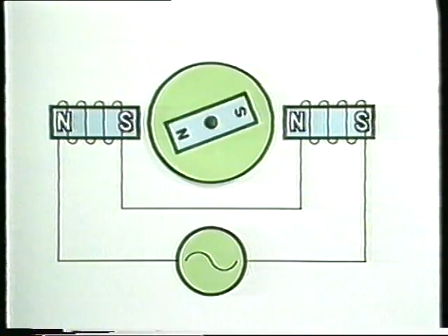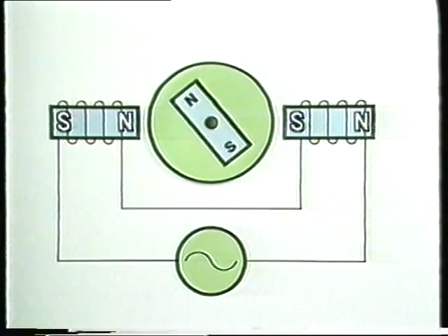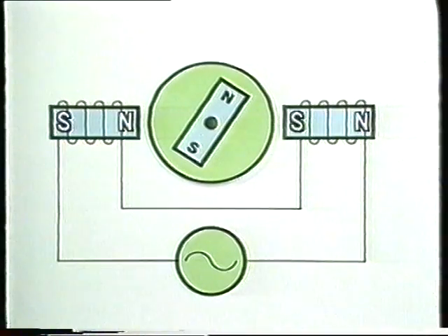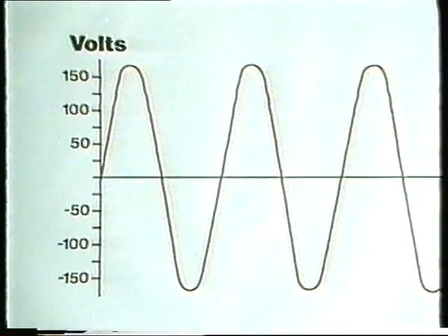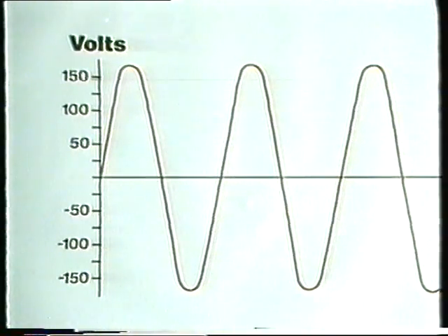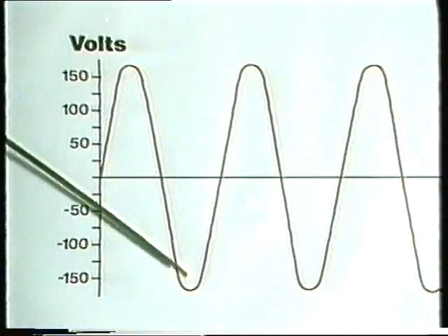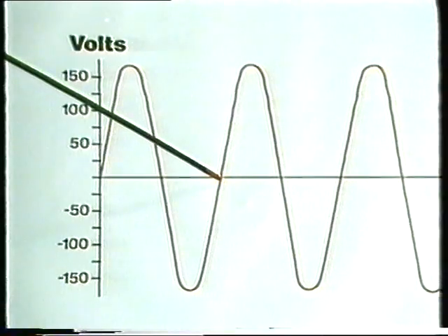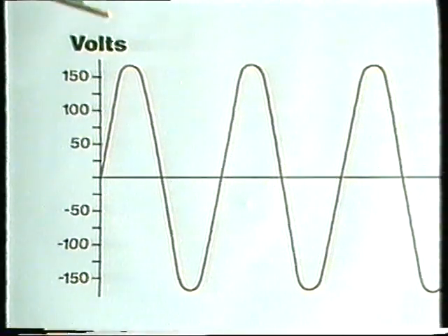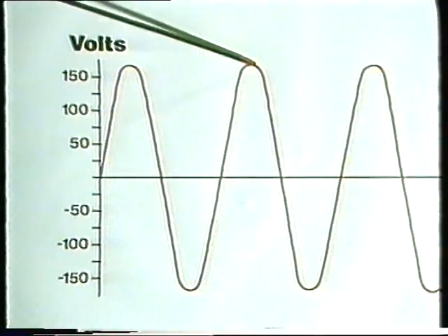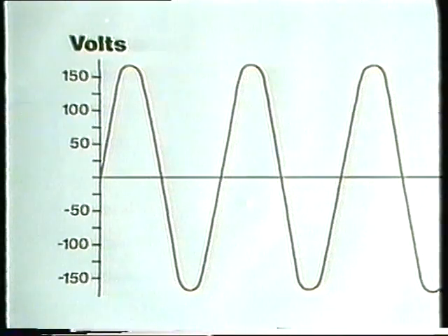How fast the stator poles alternate and the rotor poles turn depends on the frequency of the alternating current. Most AC is either 50 or 60 hertz, which means that it makes one complete AC cycle, going from 0 to positive to negative to 0 again, either 50 or 60 times a second. So powered by 60 hertz AC, the poles will alternate from north to south and back to north again 60 times a second.